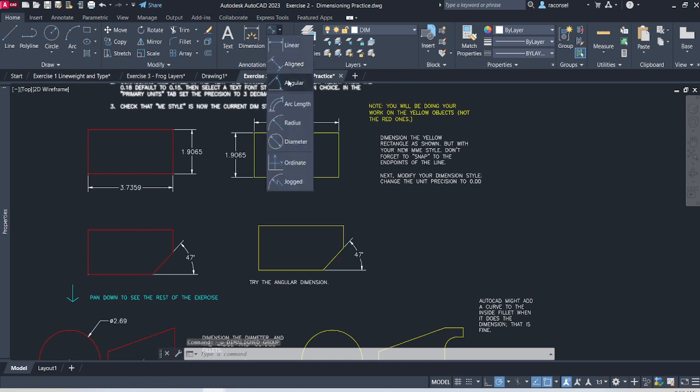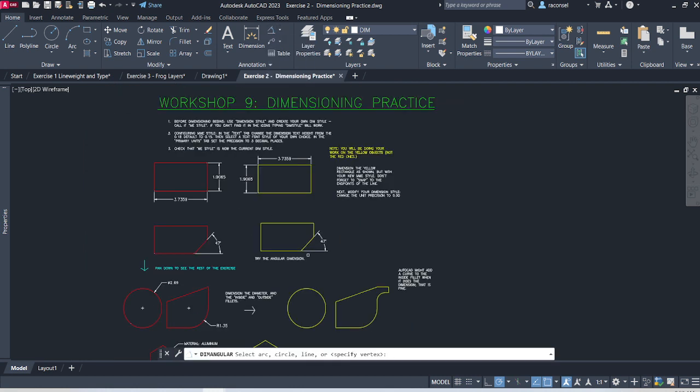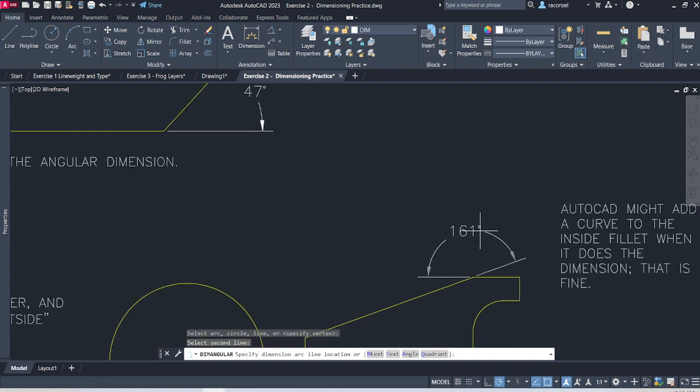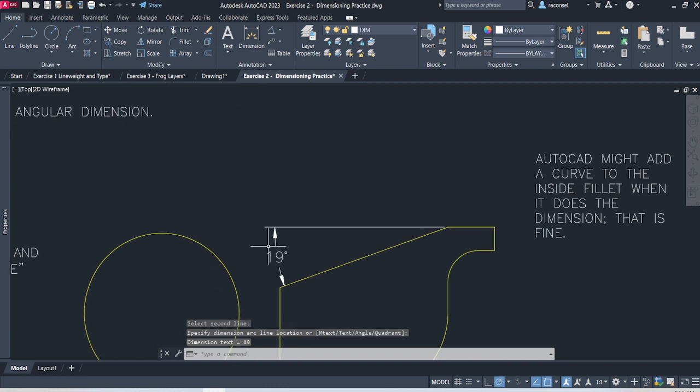And of course, we have our angular dimensions. Where's an angle? There's an angle. Pick 2 lines, drag it off. Depending where I drag it, I'm going to get it looking different. Again, my goal, have it off the part. Tell me the thing that I want it to tell me. Oops, I've made a mistake. What is my mistake in this part? Yes. I'm dimensioning to an object line. I don't want that if I can avoid it, so let me drag it a little farther, and now I've got full extension lines. Yay, I'm behaving myself.